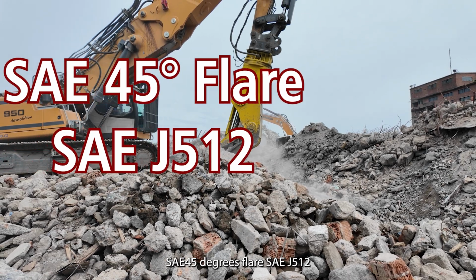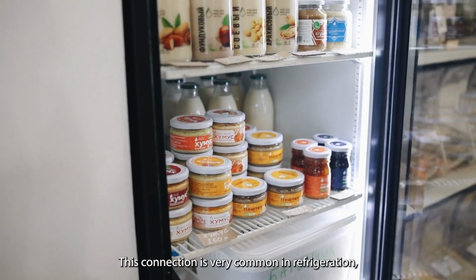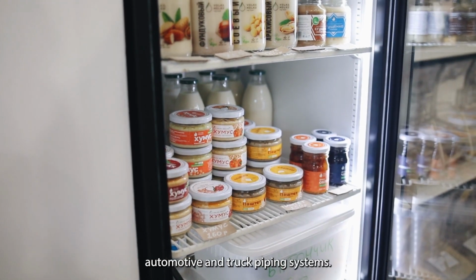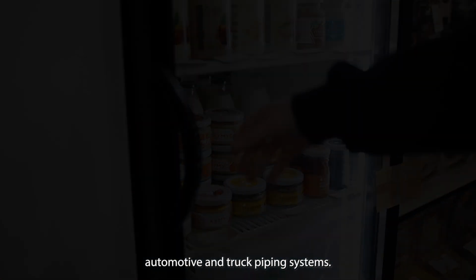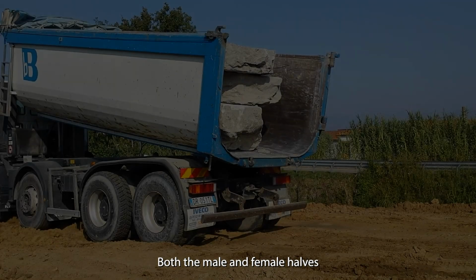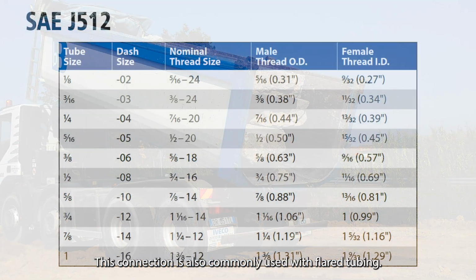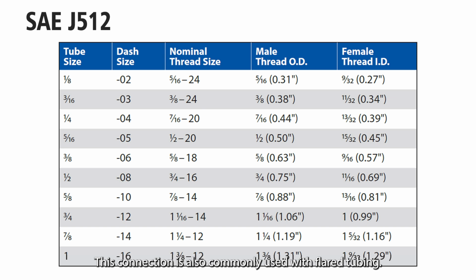SAE 45° Flare, SAE J512. This connection is very common in refrigeration, automotive and truck piping systems. The connectors are frequently made of brass. Both the male and female halves of this connection have 45° seats. The seal takes place between the male flare and the female cone seat. The threads hold the connection mechanically. This connection is also commonly used with flared tubing.